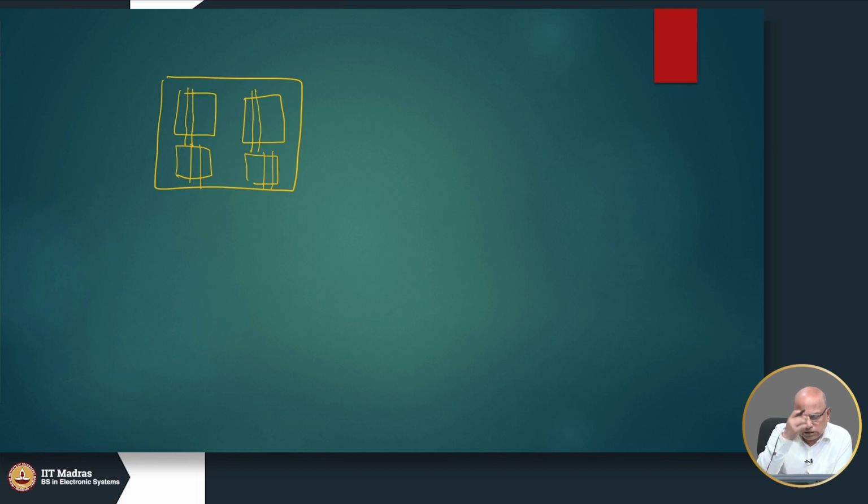The reason for that is, as I explained to you, it takes a long time to initialize the scan chains. If I have a single test vector, you will need n clock cycles to scan in the state and then one to capture the next state, and then another n to scan out the next state. So, this is a long time. It may be worthwhile to break the single long chain into multiple scan chains, and when we do that, we try to balance them out.